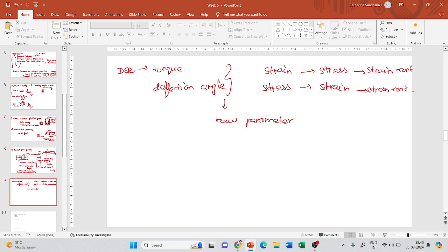Okay, so when will you use this parallel plate geometry? We will use it for viscoelastic solid-like or fluid-like materials. When it is a complete solid, you will go for a separate kind of fixture called SRF fixtures. Here the material is viscoelastic, so in such cases it is better to use a parallel plate geometry.